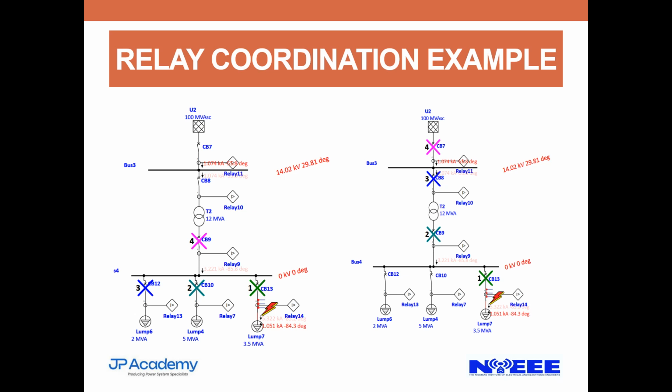Now, when I started, I made mention of this. When we say relay coordination, it is different from fault isolation. What we are seeing in relay coordination is, in case a particular relay fails to operate, what is the backup relay? That is relay coordination. Fault isolation is, let me identify the precise location of this fault, and then I should isolate only the fault.